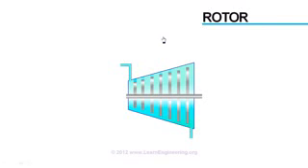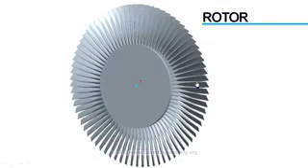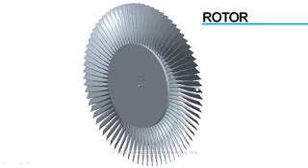So, let's have a close look at one such rotor set, in order to understand more about its working. Here it is. This is one rotor set, and you can see there is a series of blades which are connected to the hub of the rotor. In different orientations it will look like this. Or, like this. If you take a close look at one such blade, you can observe one thing. This blade is a collection of different airfoil cross-sections set together, airfoil cross-sections which vary in size and shape from bottom to top.